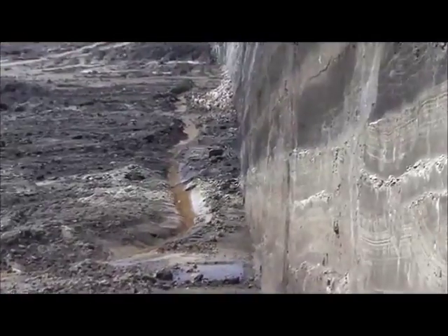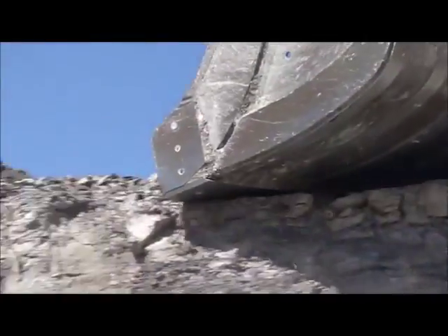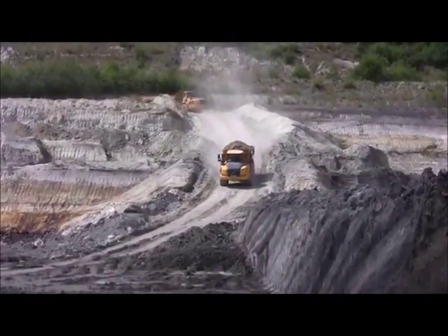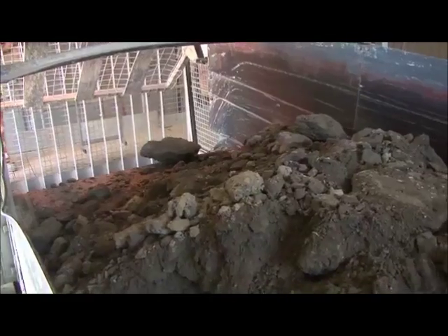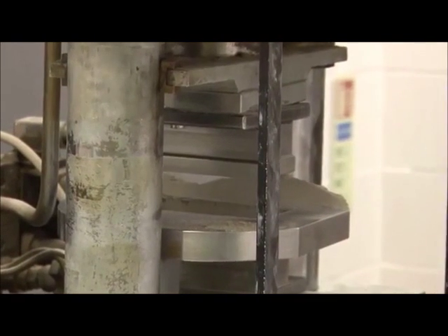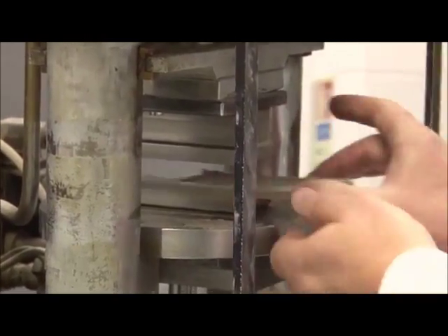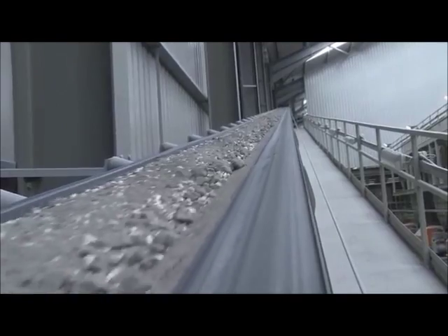The initial step in ceramic tile manufacture involves mixing the ingredients. Sometimes water is then added and the ingredients are wet milled or ground in a ball mill. If wet milling is used, the excess water is removed using filter pressing followed by spray drying. The resulting powder is then pressed into the desired tile body shape. After forming, the tile is dried slowly for several days and at high humidity to prevent cracking and shrinkage.